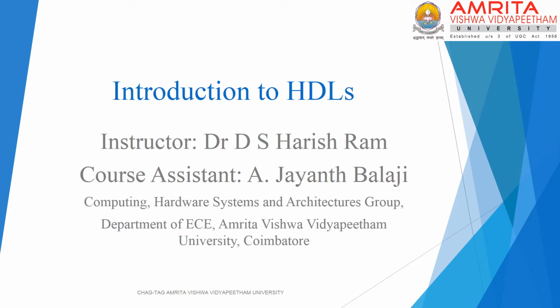We will look at the differences between hardware description languages and high-level programming languages. The concept of delta cycles, which forms the heart of hardware description language-based simulation, will be taken up. Finally, we will wrap up this lecture with an example Verilog module and its test bench.